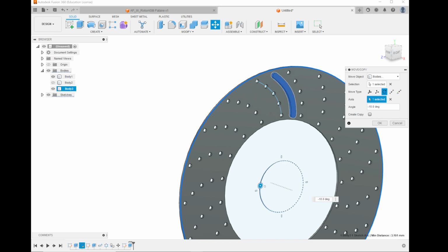So now I can obviously do it by hand, or I can put in the exact angle. I want to actually find the exact angle that's between these two holes. So we can find that out mathematically, and then later we'll pattern it, so we just have to get it working once. I know this is 360 degrees, and I divide it by 19.